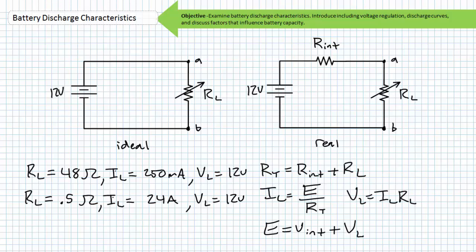In the real world, however, the internal resistance of the battery is placed in series with the electrical load. In open circuit conditions, in which no current flows, no voltage is dropped across the internal resistance of the battery, and all 12 volts is dropped across the open. Ideally, in no load conditions, no chemical reactions occur, and the battery can stay charged indefinitely. Though, as we learned in our previous lecture, this isn't really the case, and we can expect a measurable amount